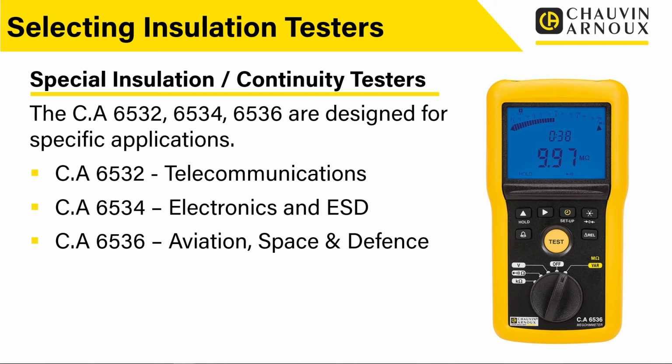We've got the 6534. This is designed more for electronics and particularly ESD, electrostatic discharge. So if you're setting up an electronics production environment or an electronics repair environment, you will have things like static dissipative matting, and you'll have wrist straps and all those sort of things to dissipate any electrostatic discharge. They need to be tested. So with suitable electrodes, you can put those onto the matting, and you can actually test those. And again, that product is specifically designed to work in that environment and be very good at doing that job.